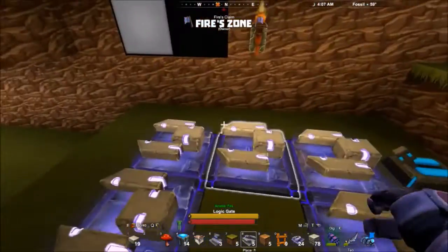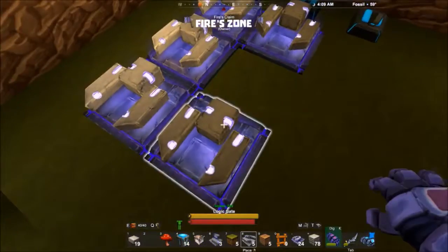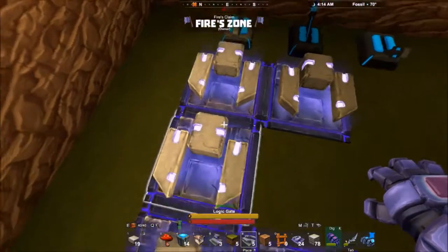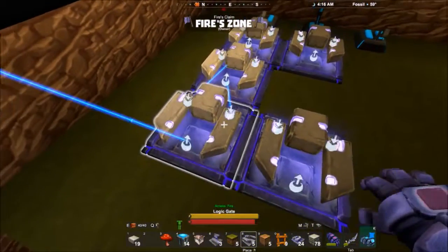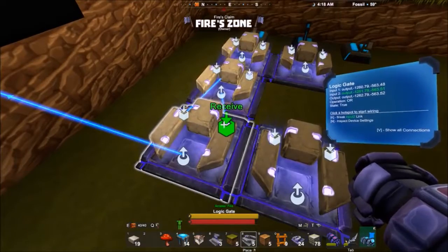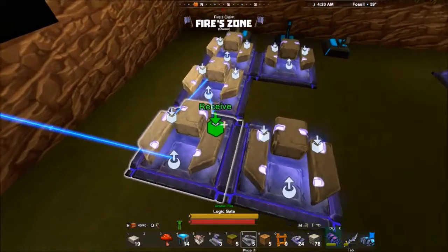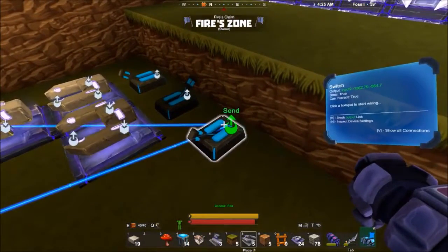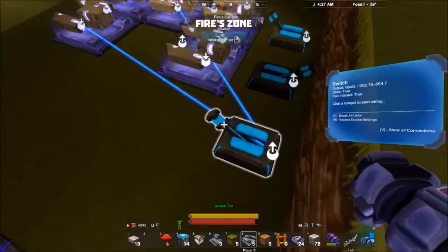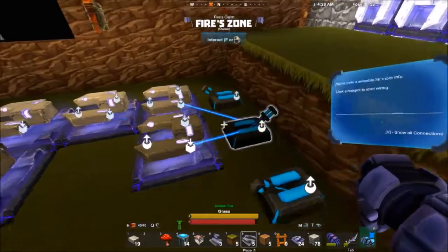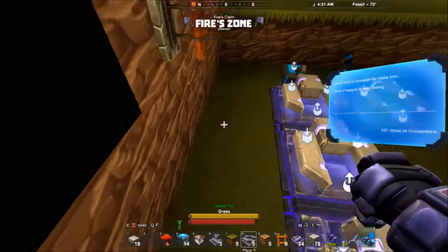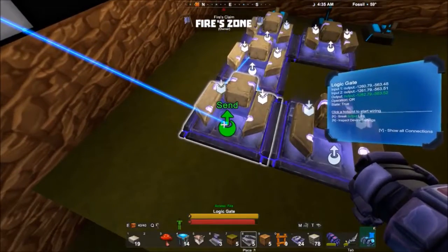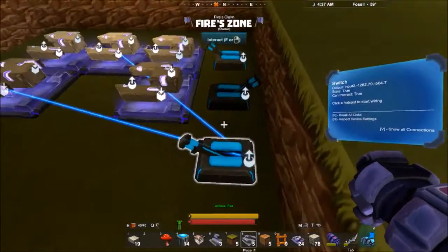So basically, this is how all of them are done. This part right here, the two exclusive OR gates, calculate the sum. The two AND gates calculate the carry, and I just need an OR gate to connect the two AND gates. You see how we have this switch right here working as a carry, and it's connected to those two gates. When you have a next one, this output right here you're going to connect to the same place where these two are connected.